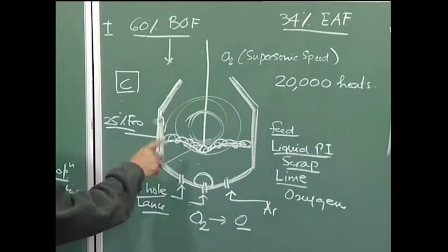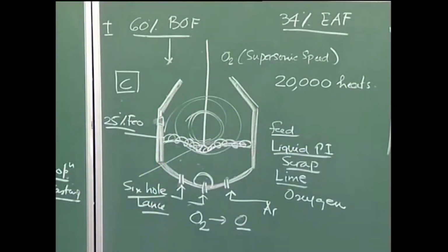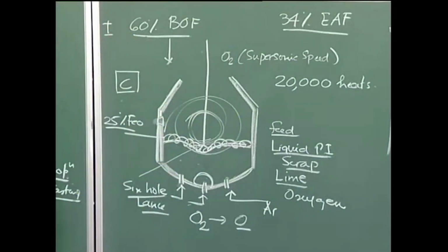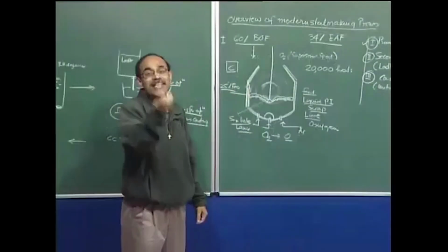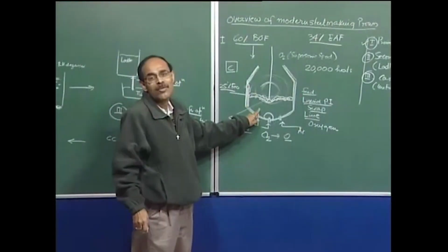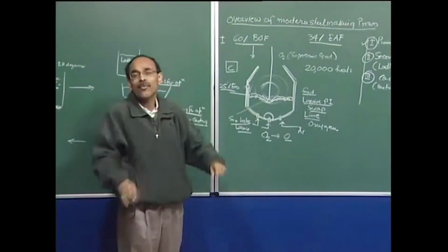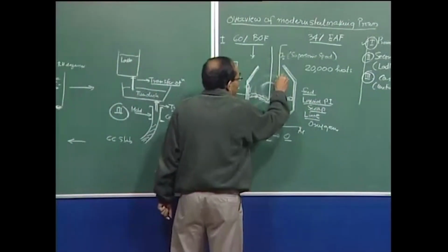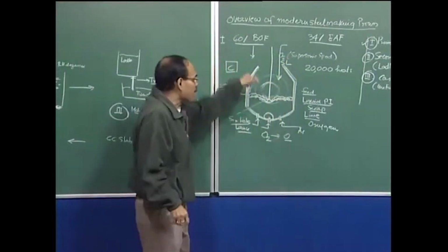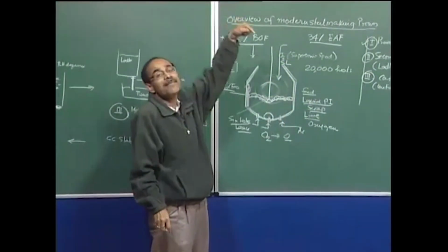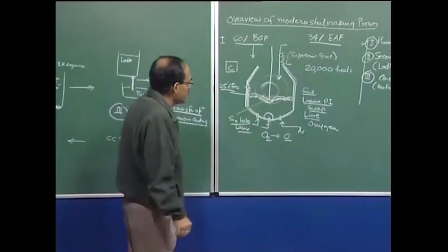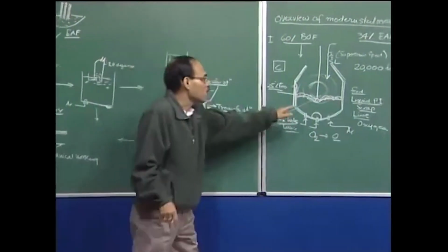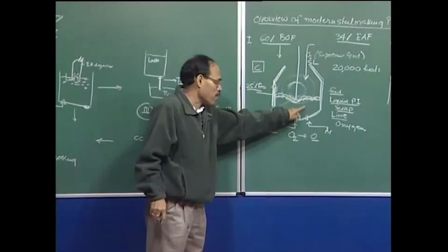After steel making blowing, we initially introduce oxygen, and then after some time we take samples to find out how much carbon is there, and then control the end blow period. Based on that simple analysis, we also use sublances. The sublance is immersed into the molten metal and a sample is collected, and we know how much heat there is and what the level of carbon content is.